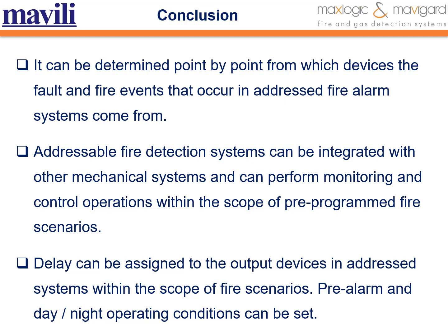As can be seen, addressable fire alarm systems are much more technological than conventional systems. System capabilities have improved considerably compared to the conventional system. For this reason, it is recommended to use addressable systems, especially in high-rise buildings, in projects where the human population and weak current systems are dense. In today's projects, the conventional system is increasingly being replaced by addressable systems.